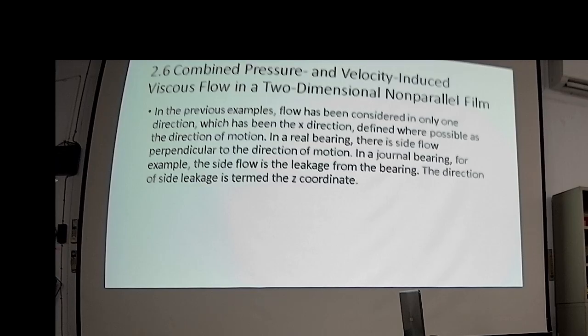We considered the fluid flow caused by pressure before. So we also consider the top plate moving with a constant speed. Then we also need to calculate the velocity-induced viscous flow. If the top plate has a moving speed, it will also make our flow rate larger.